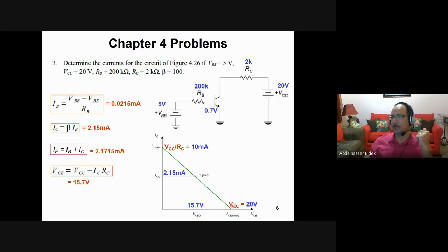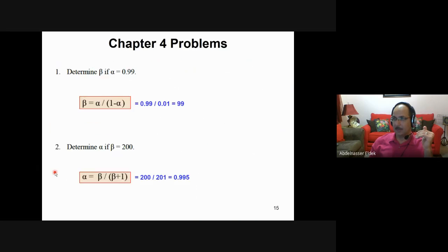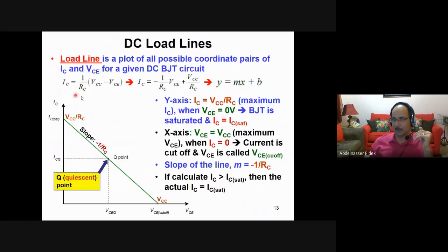According to this, we know the relation between VCE and IC, which is this one here. This one is the same as the previous one, but just looks different. There's no difference. Okay? So here you can multiply RC times IC, and then you move it to the other side. Then VCE equals VCC minus IC times RC. The same relation.